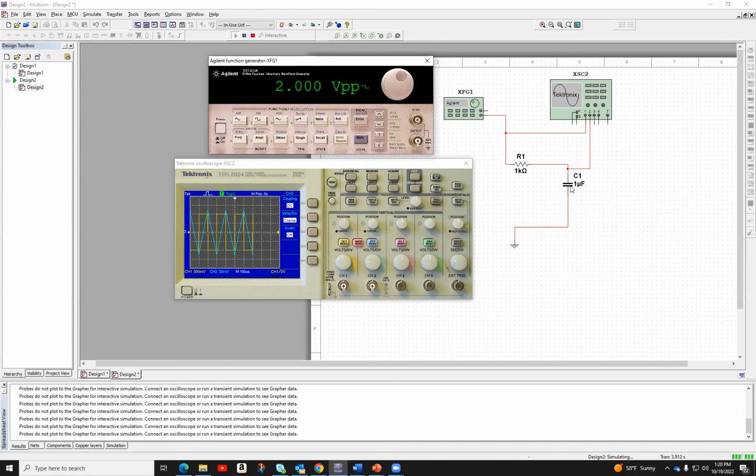And now something different happened because the effect of a capacitor is to integrate the signal in real time. And that's why you see the integration of the square wave here. Anyhow, if I change this to a sawtooth, you still see that. And if you change it to a ramp, you see that as the output, right? But I can easily change that. What else can you do? Let's see. Yeah, frequency, amplitude.